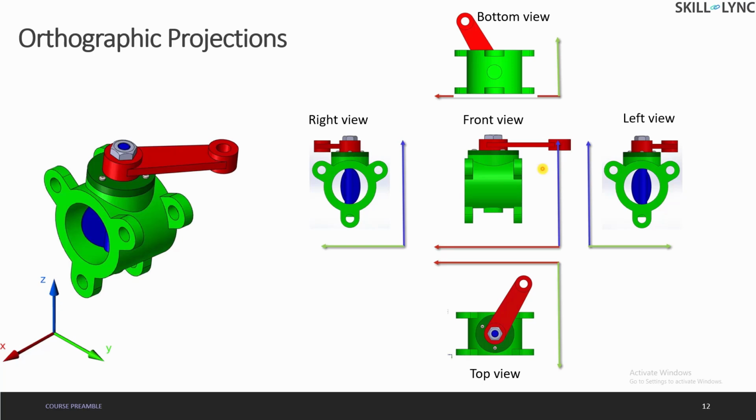So now you can also see one thing. We have spoken about the left view actually being on the right, and the bottom view being on the top. So we name it as the first angle of projection. So it means that in a 4-quadrant plane, we take the first quadrant, that is this quadrant, we keep the object on top of it and view on the respective planes. So that's called the first angle of projection. So it's represented by this symbol.